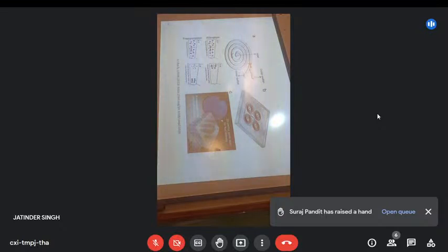These channels are not straight, they're slanted. And that means that we get particular focusing effects going on. Because we go in the curve, we've got a centrifugal force happening as well. And then we get some funky Dean circulation forces happening in the corner to keep the particles in place.